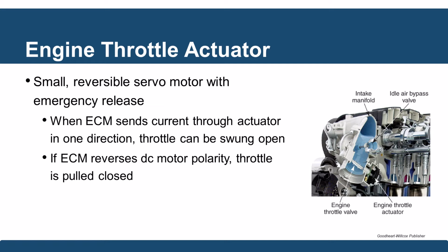We'll talk about that in a second. But the first part to understand is that the ECM will send current through that actuator in one direction to make it open. It will reverse polarity, and it will make the throttle valve close in the opposite direction.